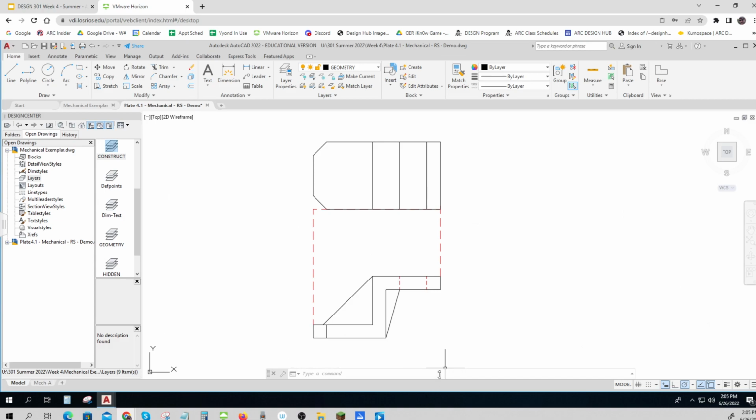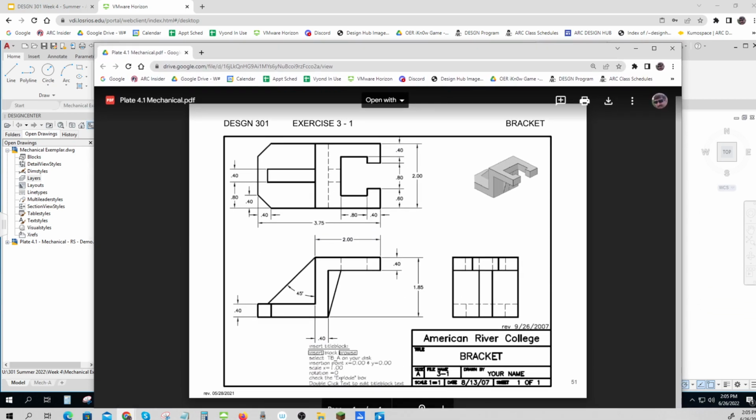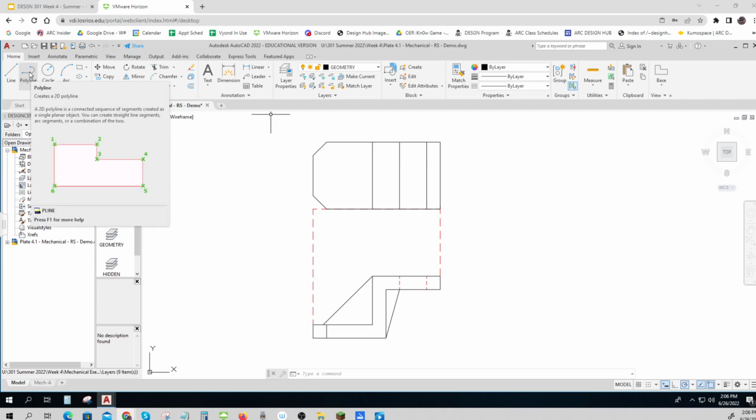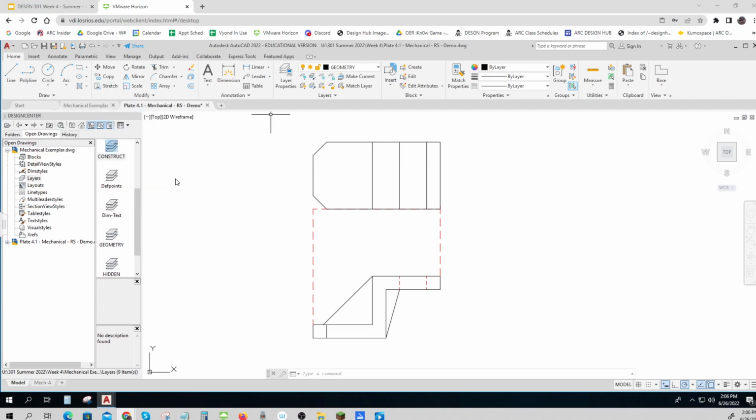That's kind of cool. And the cutout, which is going to go right here, watch what I'm going to do. So I just made this feature, that's 0.4 and that's 0.6. So I can do some offsets and then start trimming. Probably have to explode it first. Here's explode. Yep.